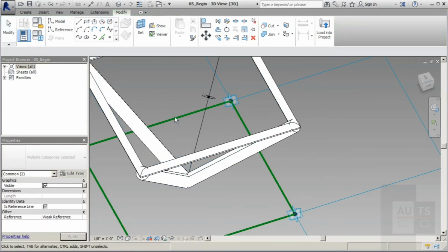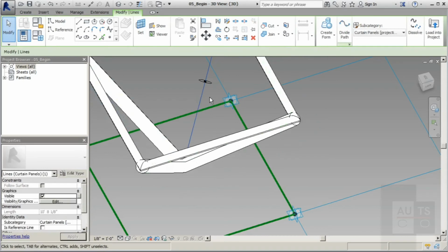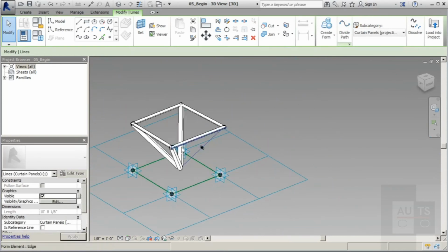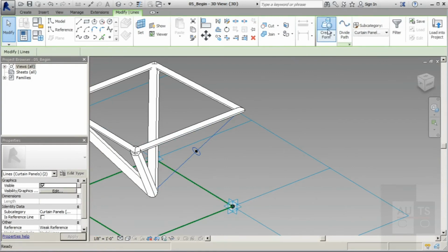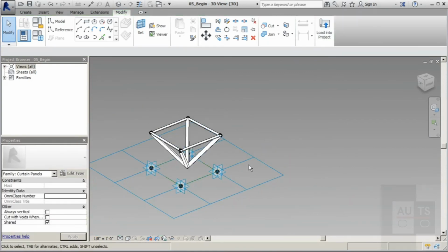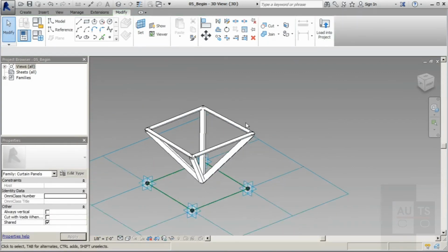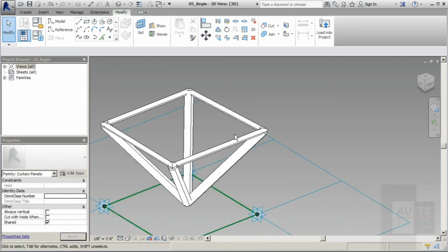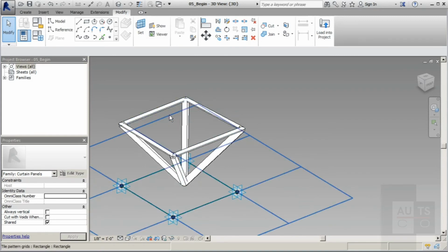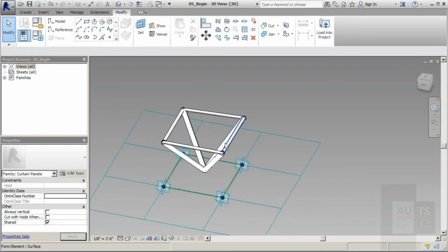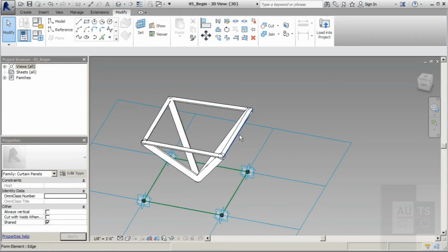Create that strut as well as this strut, simply by highlighting and Control and selecting both and create form. So we've got that in place, and the only thing we're really lacking right now is going to be the glass. Now, we could have done the glass first and then put the frame in, but if you do get the frame in first, really all you need to do to get the glass in is try your best to kind of locate that simple clean line that you see that's highlighted.